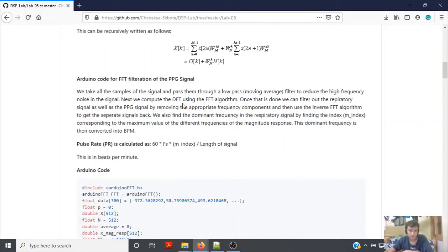So what I mean by that is, you don't get a direct frequency correlation, you get a frequency correlation to an index. The reason that follows is because we use a sampling rate. So we have a relation that is f, which is the frequency, divided by the sampling frequency, is equal to the index divided by the length of the signal. This relation holds true because our entire frequency has to lie between -1/2 and 1/2.